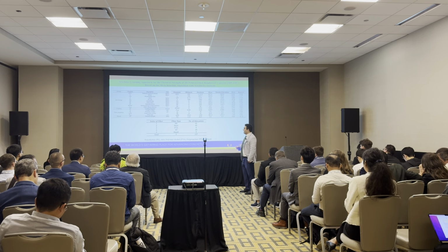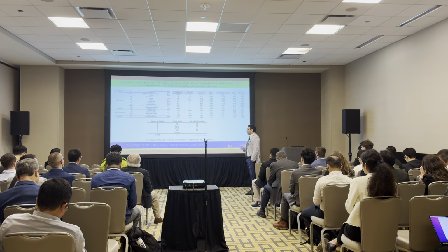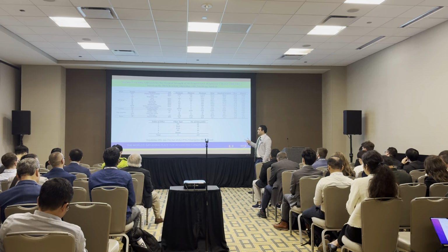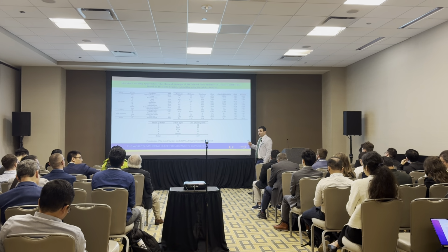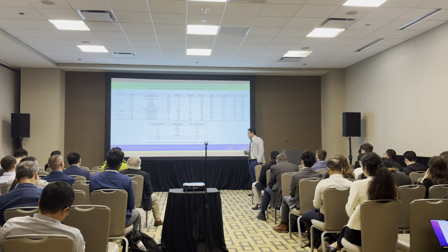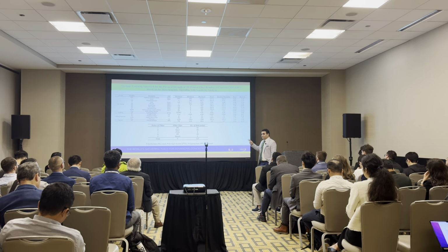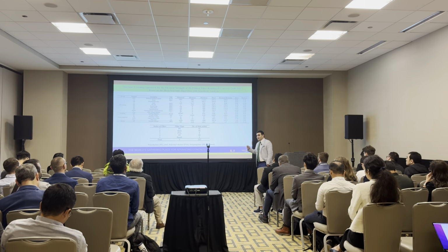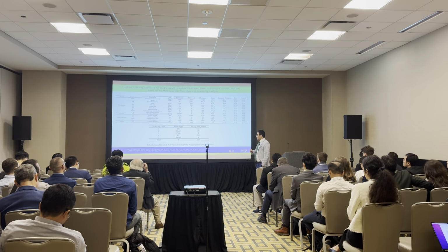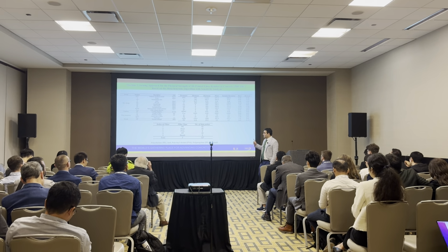These are the parameters that we have: the Portland cement, water, sand, fly ash, ground slag, silica fume, and some others. And we are going to predict the flexural strengths of our models. But here we use some fiber inside the 3D printing: PE, ST, PVA, PP, and basalt.